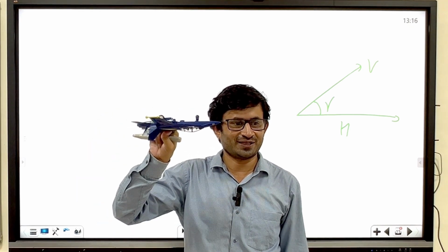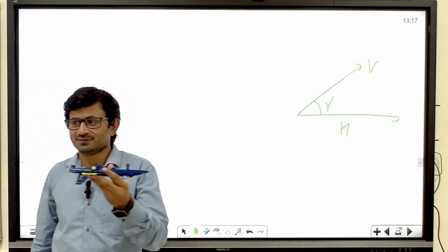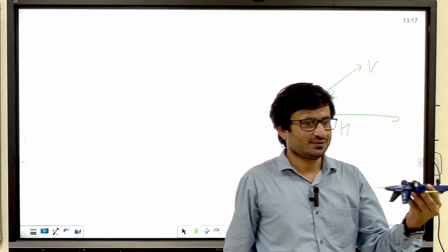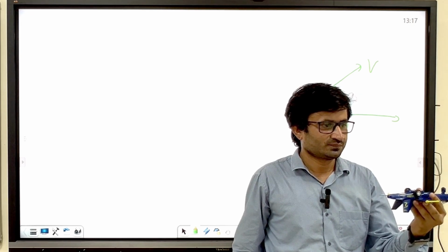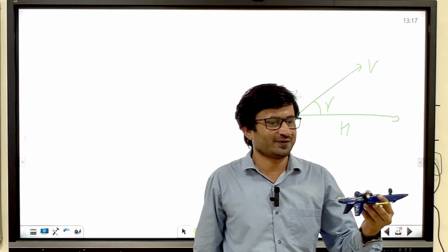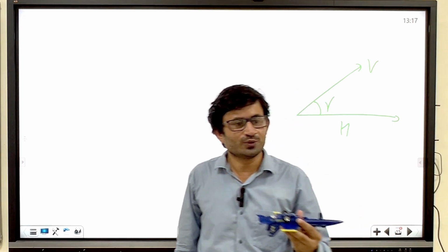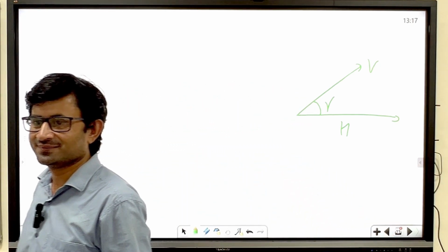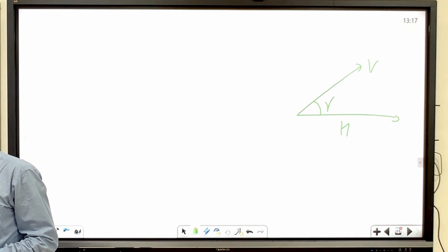This case, just at point B. Can aircraft fly inverted? Aircraft can fly inverted, right? So if the flight is steady state level flight, what is the flight path angle? 0, right? So at this point you can say it is 0 only. So are you aware of CL naught? You use the cambered airfoil where you can fly at negative angle of attack also.